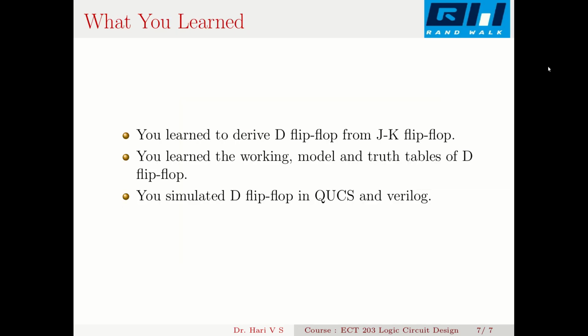Now what you learned in this video is that you learn to derive D flip-flop from JK flip-flop. You make J equal to K complement and it becomes a D flip-flop. You learn the working model and truth tables of D flip-flop. Then you simulated D flip-flop in Qucs and Verilog. And that is the end of this video.